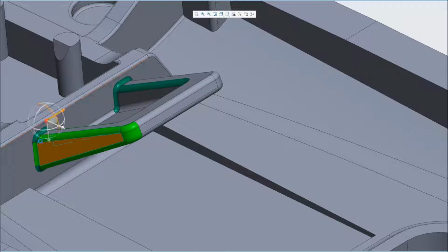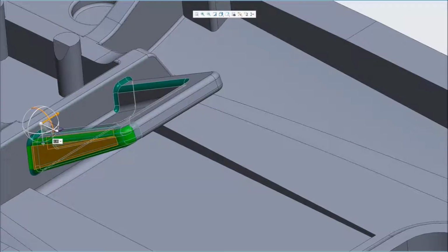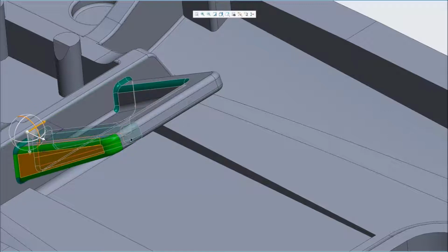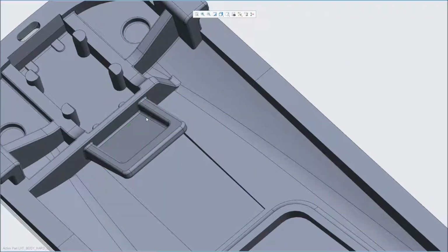And we'll move using this edge as our direction reference, and we're just going to tell it in here, okay, let's move by 1. All right, Creo shows a geometric preview, and whenever I select OK, yep, there we go. Now I have that pocket expanded, right?